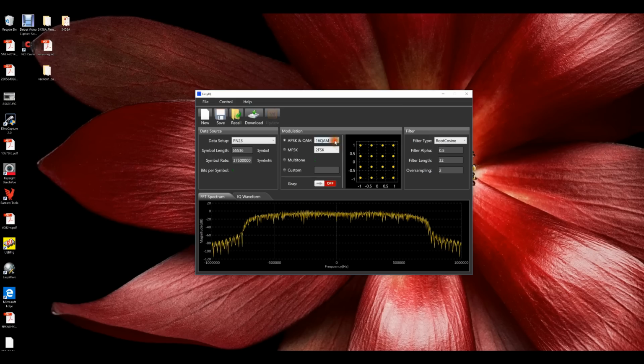Now the constellation, let's go all the way to 256 QAM, and it's unfortunate that it limits you to 256 QAM, because with a 16-bit DAC, you should be able to target much higher constellations, and this can be used for more modern communication systems. No reason to be limited to 256 QAM.